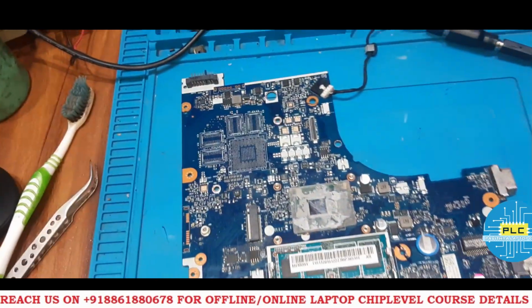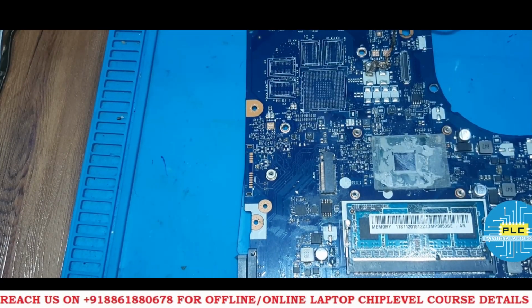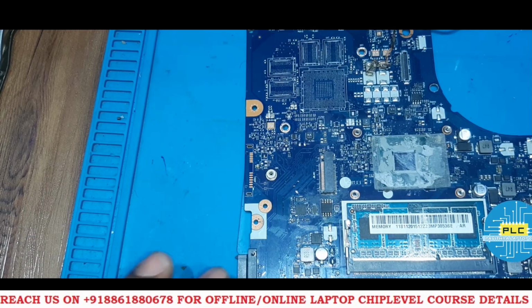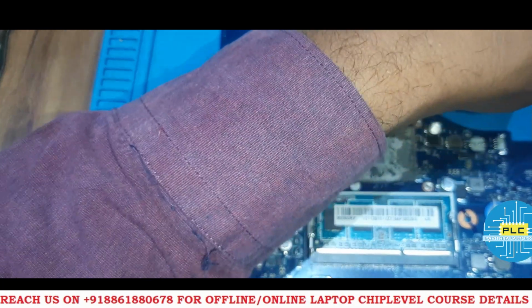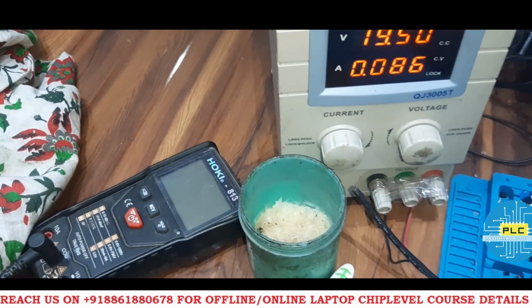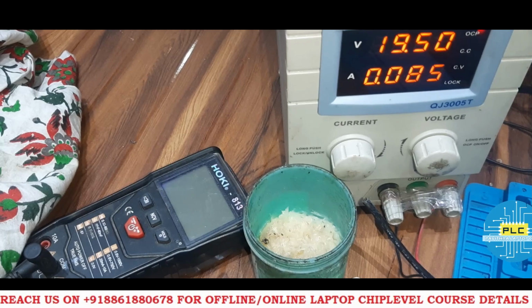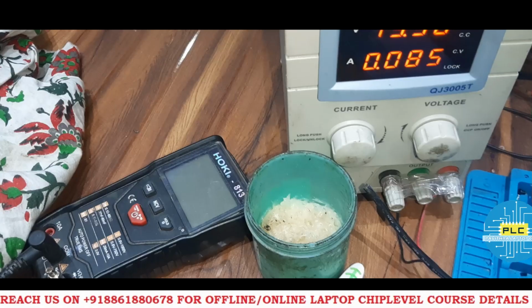Okay, so now I'm going to disconnect one more jumper. Now I removed PJ504. Actually it's the plus 0.675 VS section. Now we will check what the amp rating is. There is not much difference, actually the difference is only 0.02 amp. It's 0.085. Previously it was 0.088, I think so.